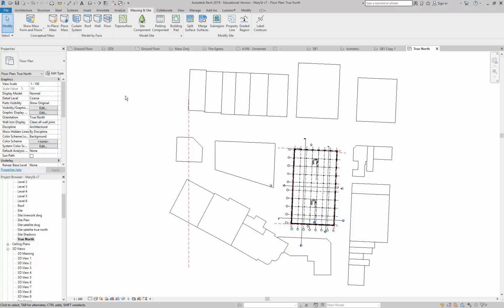Yeah, I'm very confused by there's some really weird levels and stuff in there. Right. Yeah, I didn't make those levels. But it's going to ask for your help to clean it up. Well, to give you a tip there, if you want to make it a much cleaner file, you could rebuild it, but if you get a new blank file, and then insert the ones I've given you into that file as a link. Exactly. And that way you can detach it or just remove it. Well, you can turn the levels off when you're linking. Yeah, you can.